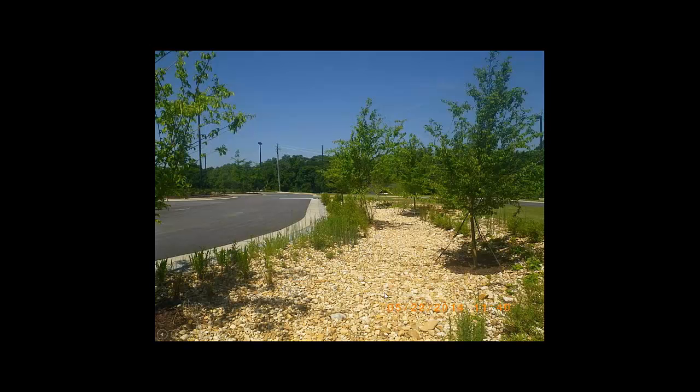So we're putting it into this engineered, enhanced bioswale. Underneath the river stone you see here are amended soils, sands, and organic material, which help with soil infiltration and also absorption. Down on the end is an overflow mechanism, which sends this down to a constructed wetland for further treatment before it's discharged into a stream or a river.